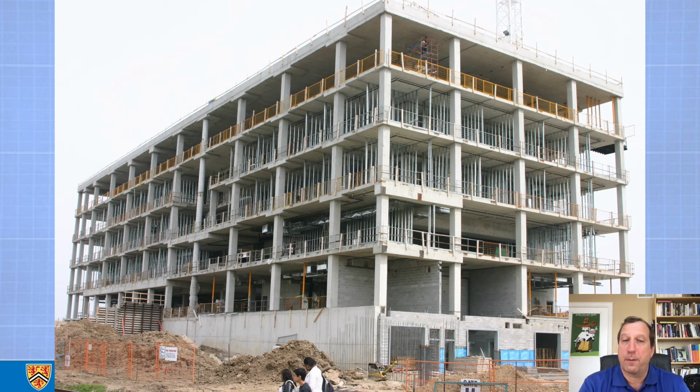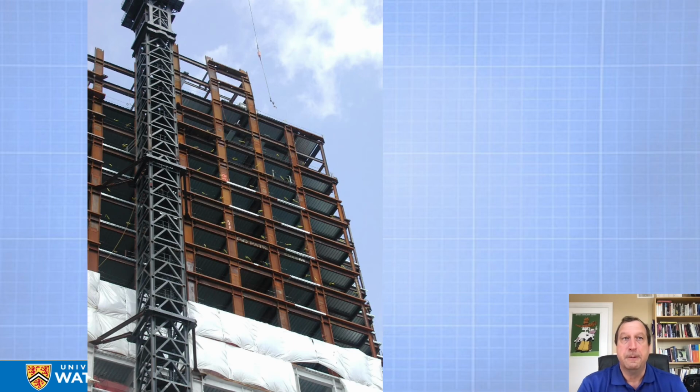The elevator core probably provides some lateral resistance, but the moment resistance of the columns to slab will also provide a lot of lateral resistance. And in steel buildings that are tall enough, we routinely will see really heavy steel sections that can be used to frame an opening. And this is a rigid moment system. It's how First Canadian Place in Toronto was famously built. Had a lot of economic advantages because of construction speed and simplicity.